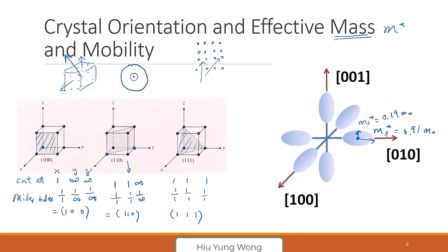From the basic physics, we know the mobility is equal to q times tau divided by the effective mass. What is tau? Tau is just the mean free time, right? The time between which you get scattered, when you get knocked by someone else. It's like, again, an army array of people who line up, and you try to run into there.